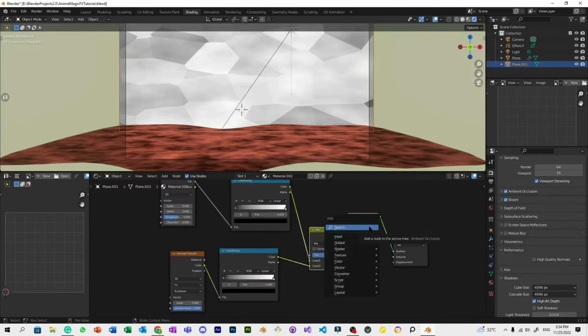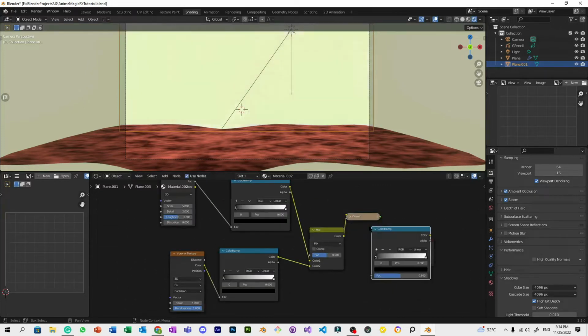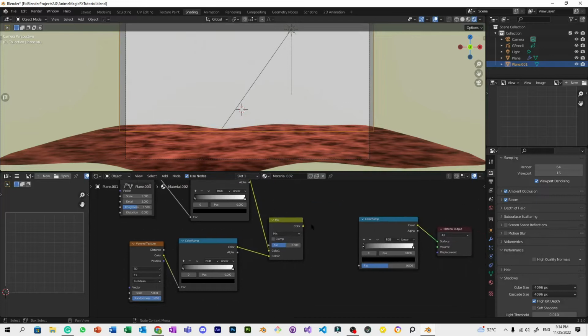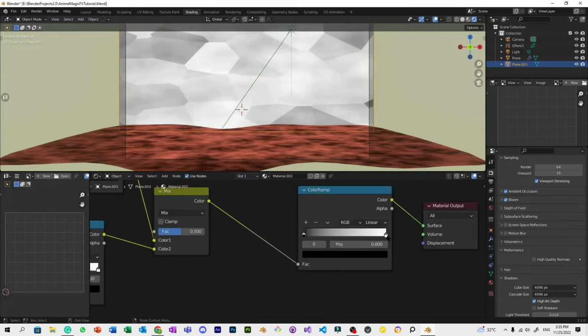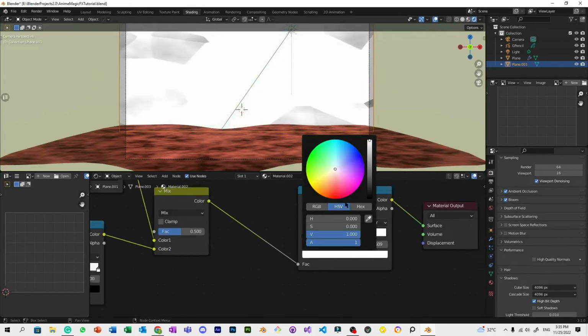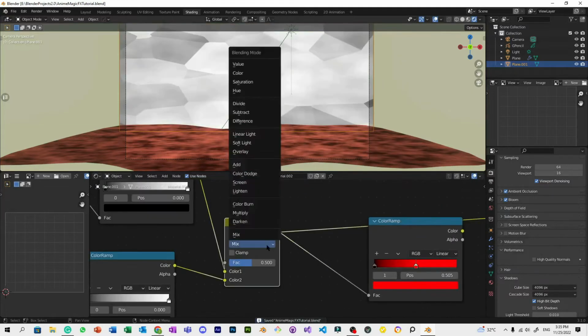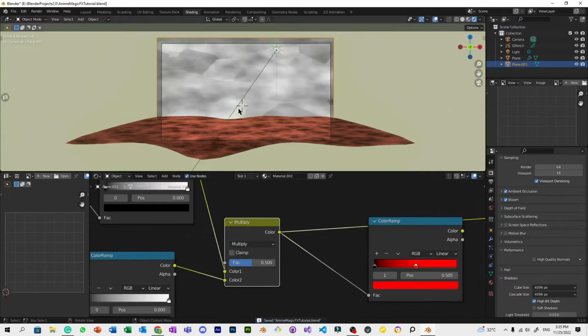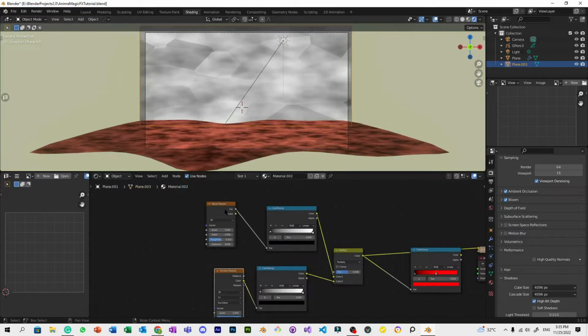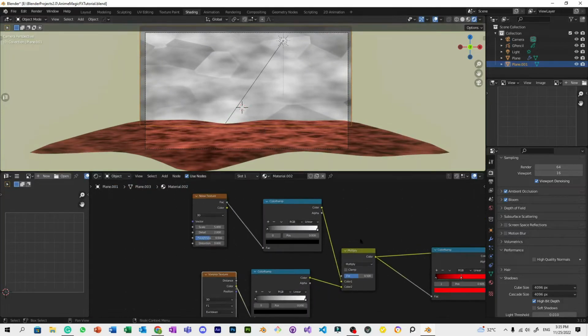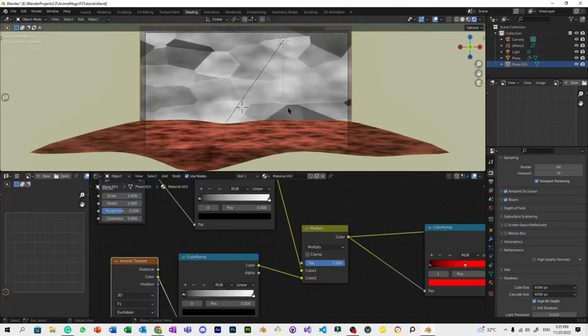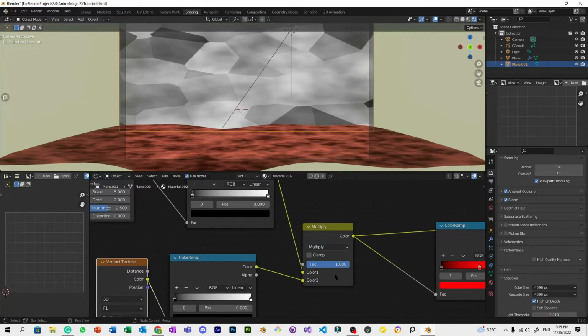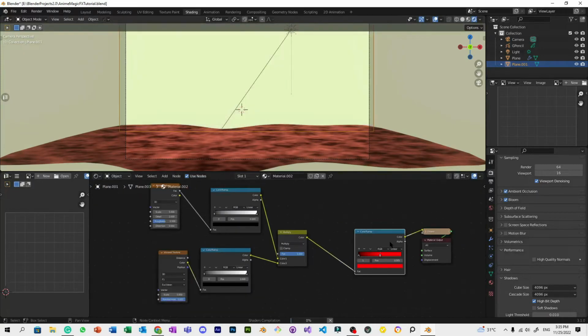So we need an end color of this, which will be color red, as you can see in the main scene, right? So to make this color red, then simply turn this into red. But we're not done. We need to multiply this. Why multiply? So the two textures will combine on top of each other. Then one is completely combined. Multiply, then one. Then as you can see here, it looks like this.